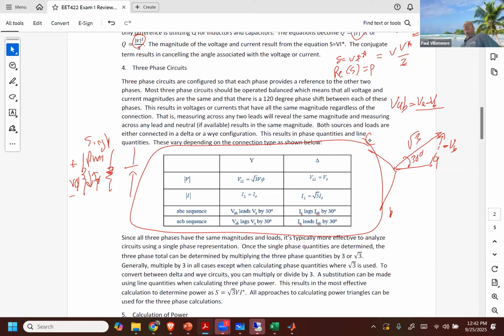So if you get stuck, just draw a picture. I can see I've got 30 degrees there by drawing it, right? When I just did the negative VB, that wasn't a trick, right? Everybody's seen that from previous math. When you're subtracting a vector, you just phase shift it by 180 degrees, and then you tag it on to the tip of the other vector, and then you just add it. Okay?